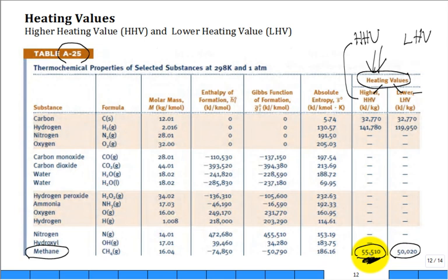So if you want a lot of heat out of your reactor or combustor, and I know this is a positive Q in, so a large negative Q dot over N dot, tell me a little about the temperature of the products that you want going out. You want them to go out hot? If you wanted a large Q dot, would you want the products to be hot, or would you want the products to be 25 degrees C?